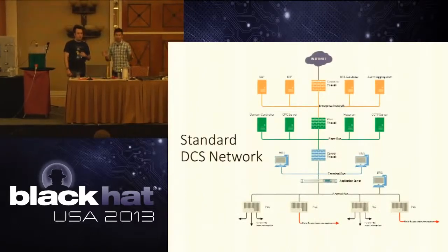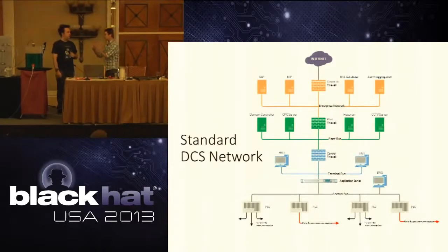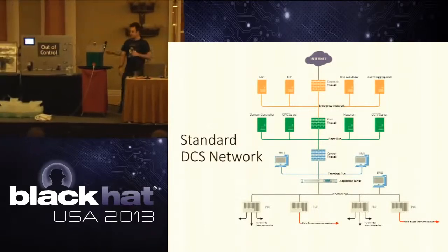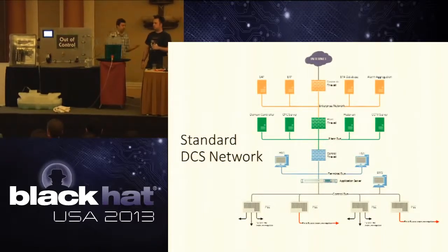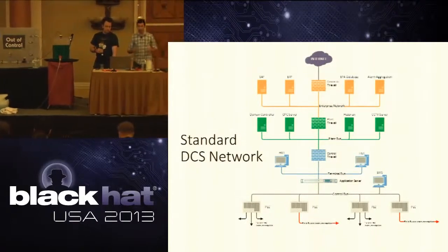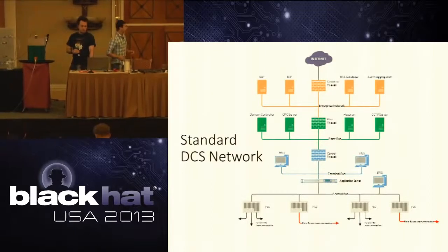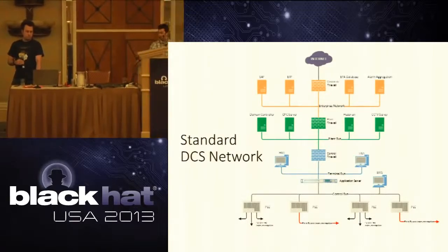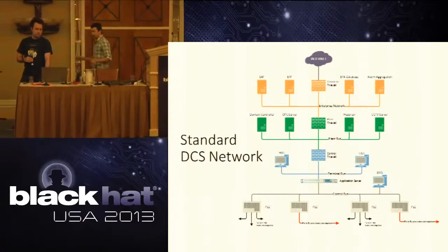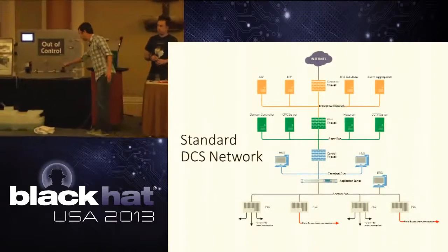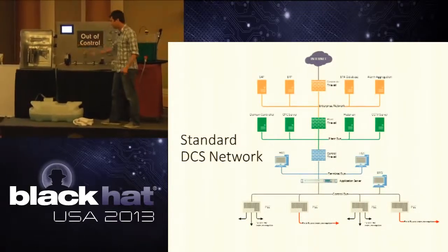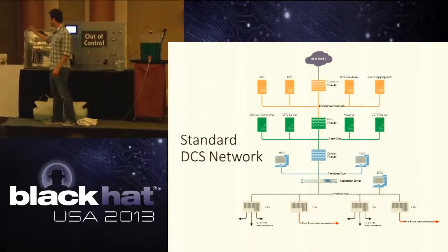Okay, so when we talk about a control system, we have this small guy right here, and he's just a controller with some field instrumentation and an HMI. But there's a lot more to it. So what we have here is a top-down model of what a real control system looks like. If we start from the very bottom, we see our field instrumentation right here. This field instrumentation is controlled by the controller itself.